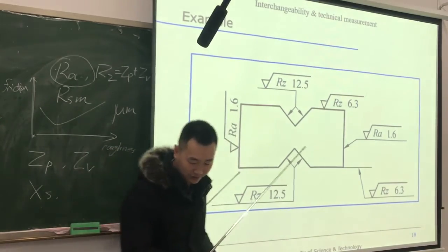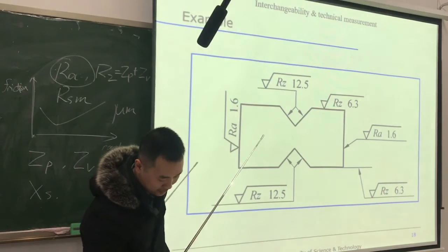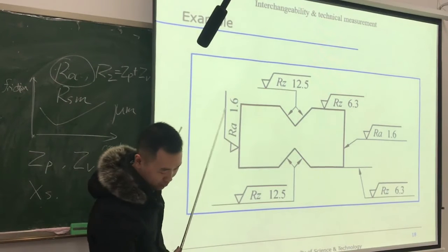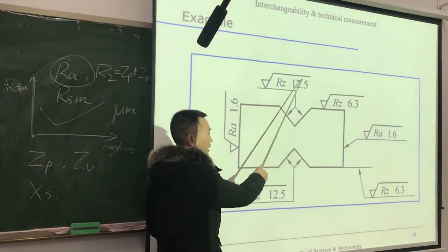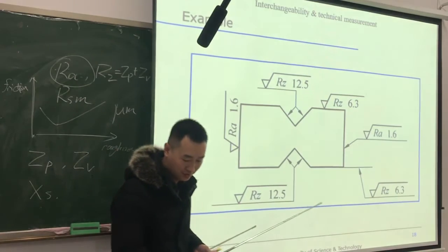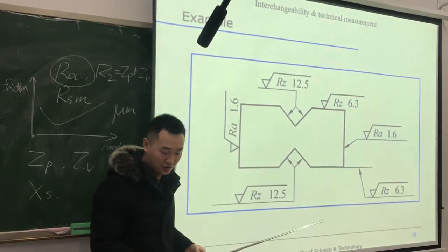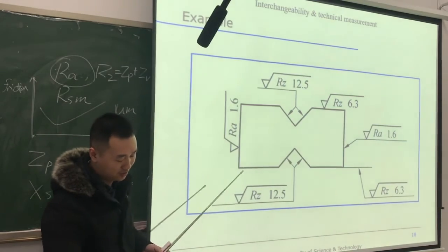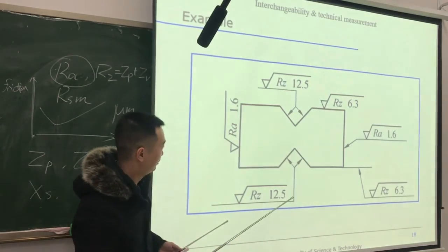These values are derived from the preferred value series, and when you need a value, you need to find the closest one and choose it from these two tables. It cannot be selected as you wish. You can only select specific values from these two tables.